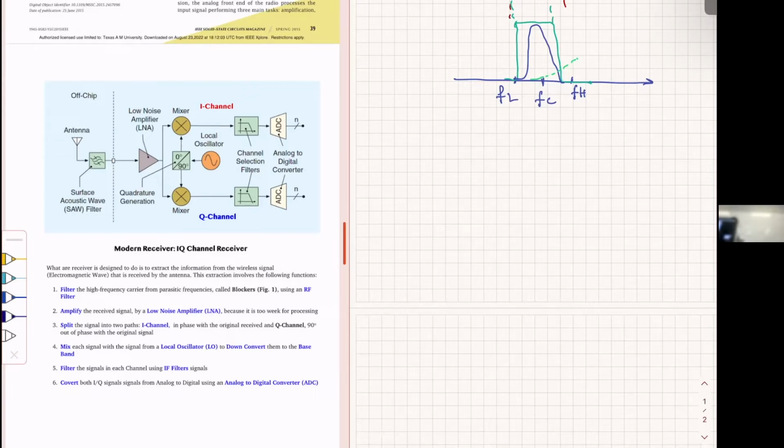All of these frequencies have the same information as the original signal, so we don't need all of them to find the original information that we used to modulate the signal. So we want to keep only the low frequency, from here and from here. So we pass them through two low pass filters. That's how you show a low pass filter.